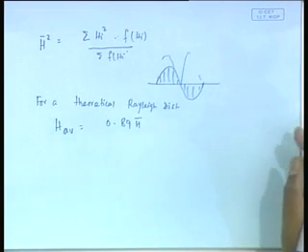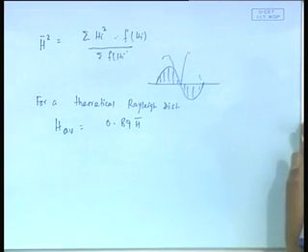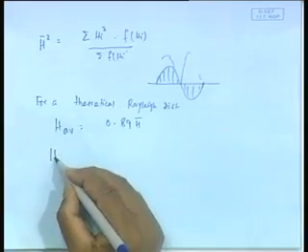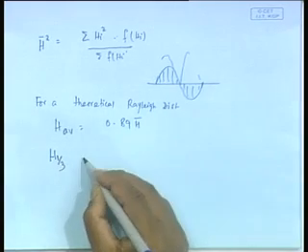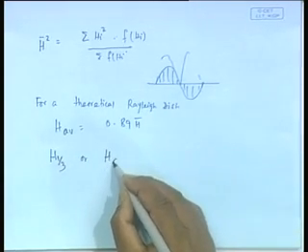The question is, supposing I want to signify the severity of a wave, should I use the RMS value, should I use the average value, what should I use? Here comes a very important concept in our subject of ocean waves, which is known as H1/3, or loosely it is called H significant.